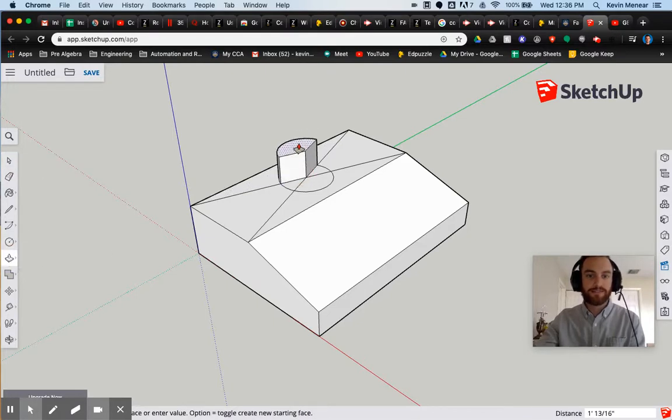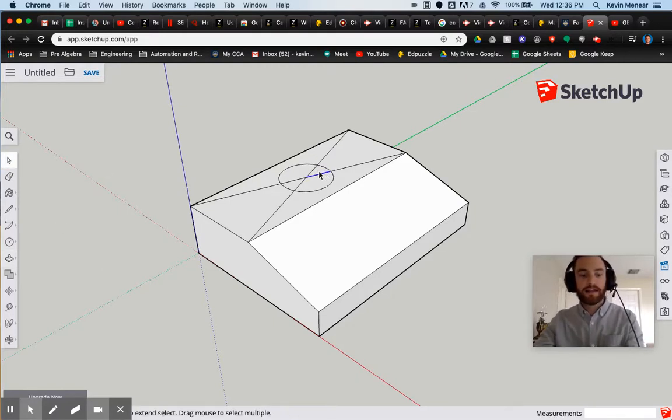It's going to select individual parts, and I don't want that. So what should I do? Just delete the sides. Now, if I select and hold Shift, I can delete them all at once. But I don't really recommend doing that because sometimes you're going to make mistakes. So I recommend deleting them one at a time. Click, delete, click, delete, click, delete. And now look, I keep hitting this face by accident. I don't want to delete that. If you ever do something you don't want to do, just hit Command Z or Control Z, and it'll undo it. Okay? So then delete this line, this line, this line, and this line. I only put those there because I needed to find the middle.